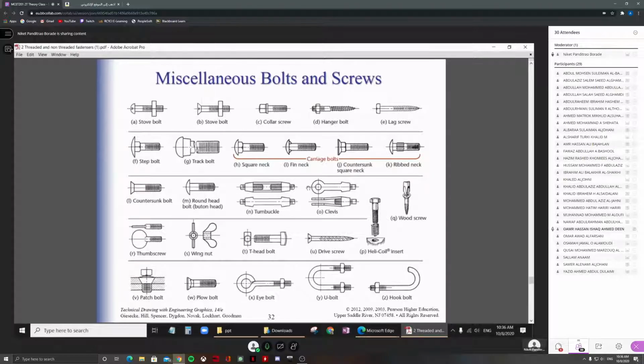Generally it is connected to some cable or some machine mechanism. It can be a lever also. If you want to increase the tension, you turn the body of the turnbuckle. Because one side is left hand and the other side is right hand, both will come in or both will go out, increasing or decreasing the distance between the two fixed points of the eye bolts. So it is basically for increasing or decreasing the tension.